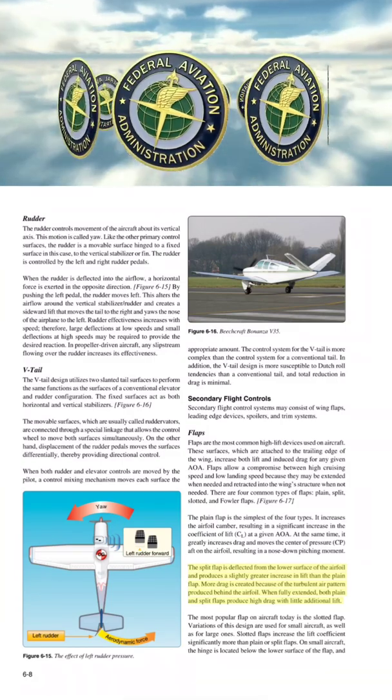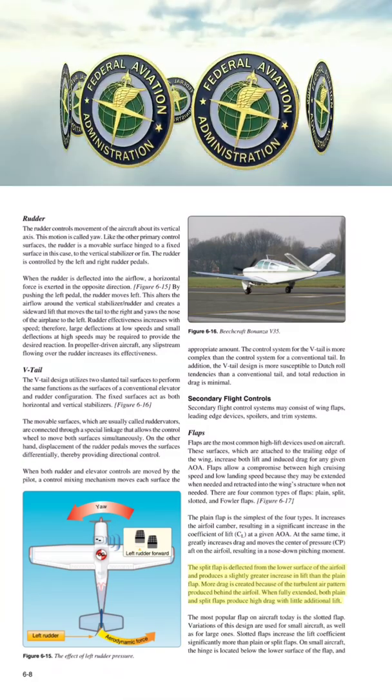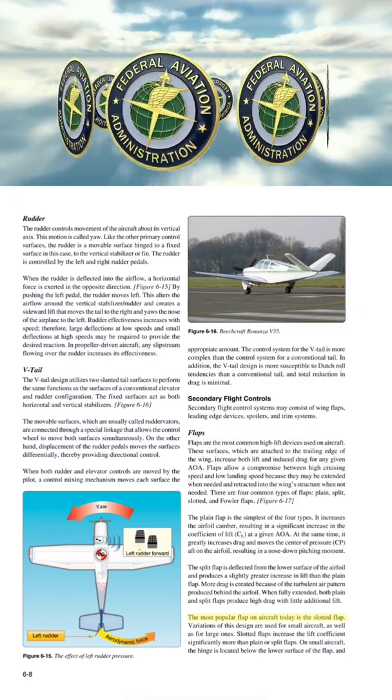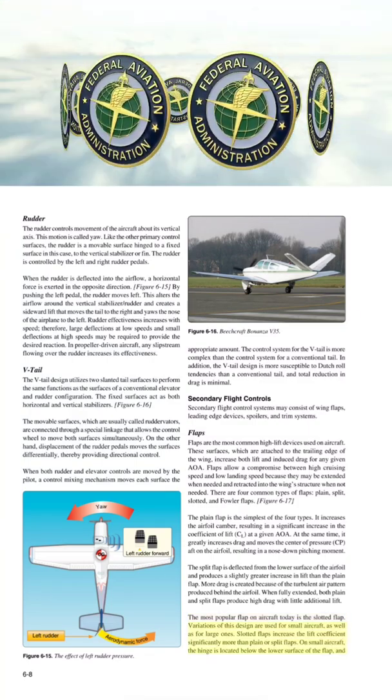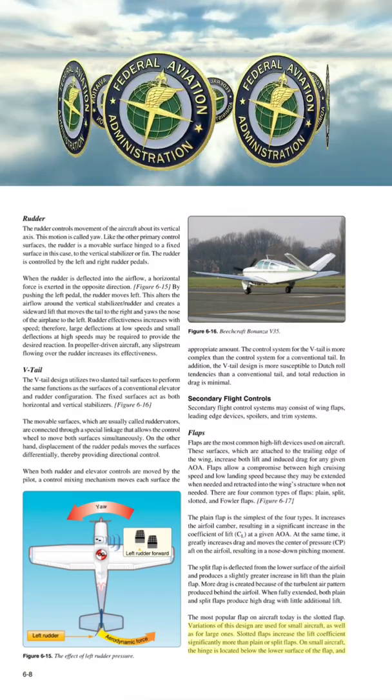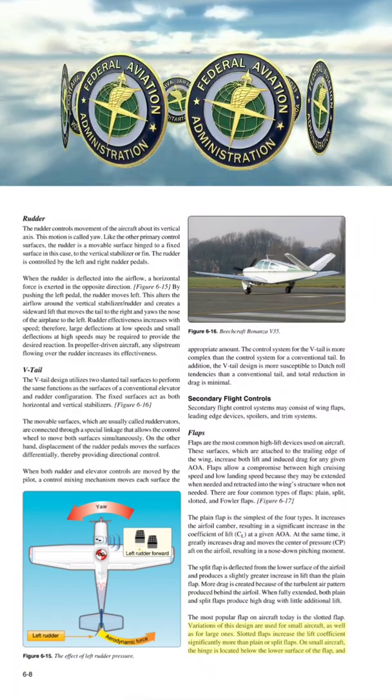When fully extended, both plain and split flaps produce high drag with little additional lift. The most popular flap on aircraft today is the slotted flap. Variations of this design are used for small aircraft, as well as for large ones. Slotted flaps increase the lift coefficient significantly more than plain or split flaps.